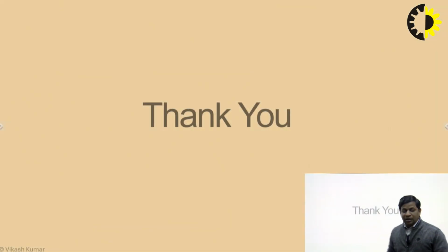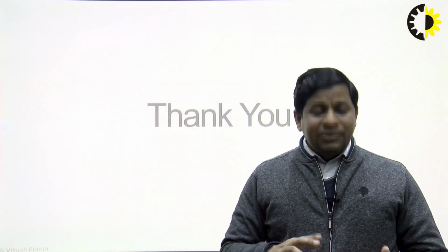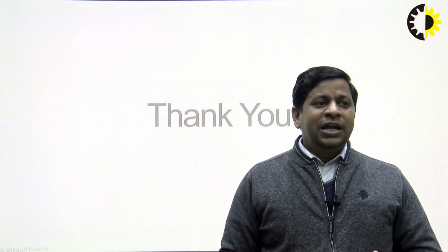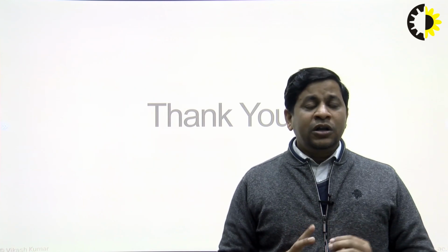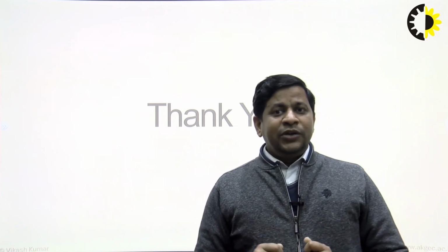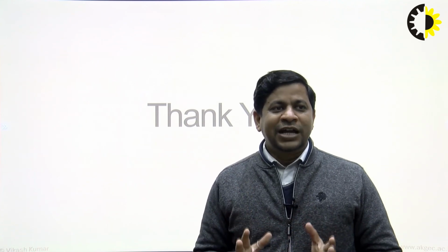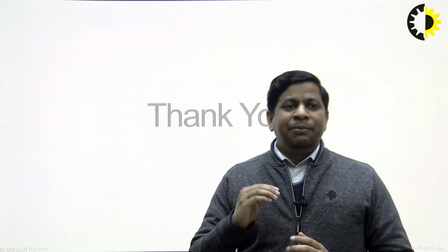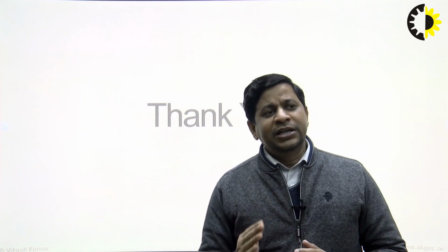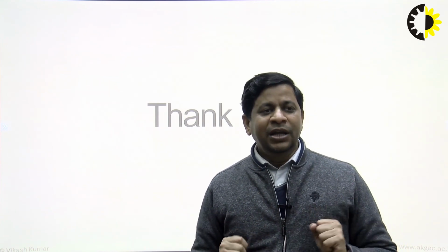So this is all about singularity that we have discussed here, and this is the most common problem that you can easily target or avoid if you have some basic knowledge about it. Simulation is one tool where you can simulate and easily avoid it, or while jogging, you can jog your robot at slow speed, and if such cases arise, you can avoid them by touching up some new points so that this singularity can be avoided.